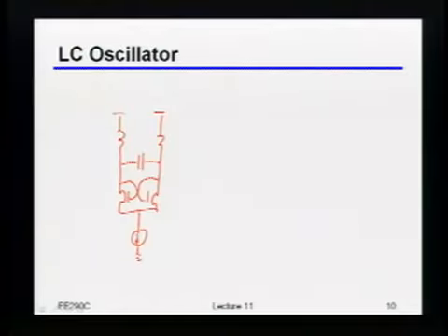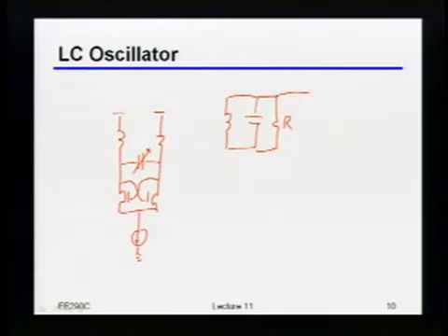But the idea here is, and I'll add one important thing, because we are doing this inside of a PLL, you're going to have to tune something. Generally, you're going to tune the capacitance. The general idea in this kind of oscillator is that if you had some parallel RLC network, that R is just representing the loss in the network. All you're really trying to do is put a negative resistance in parallel with that loss to make sure that it's perfectly an oscillator, okay?